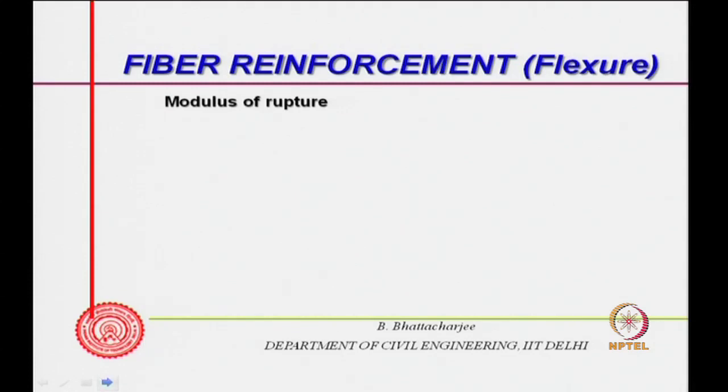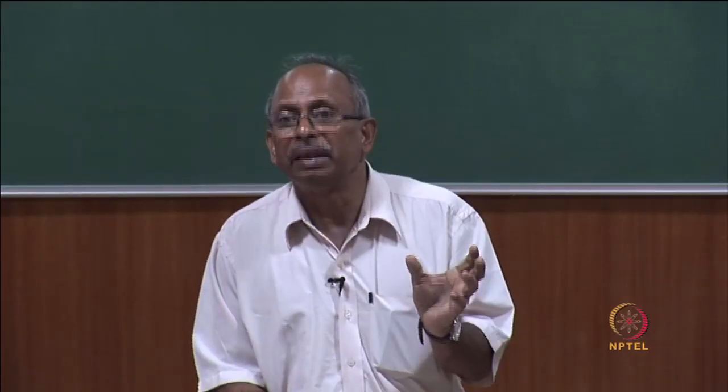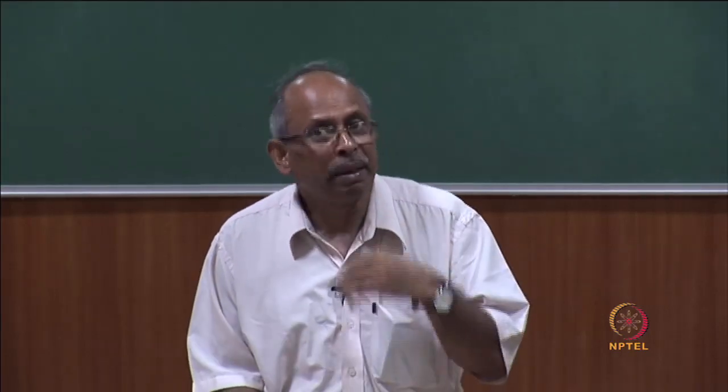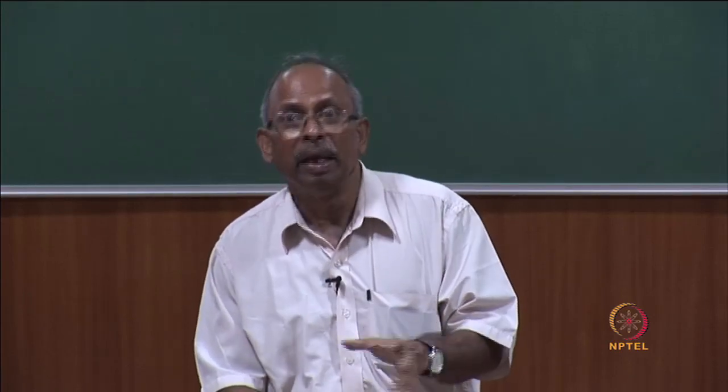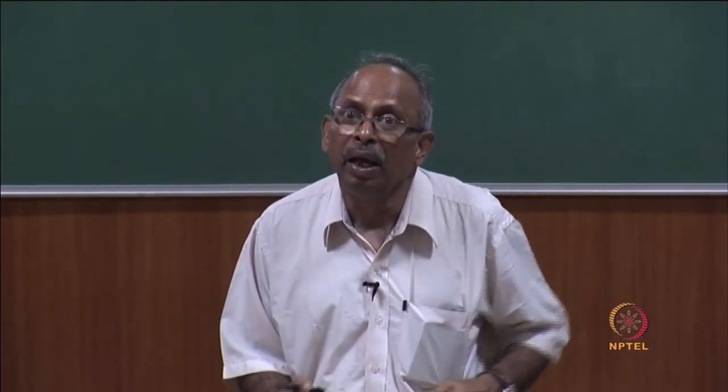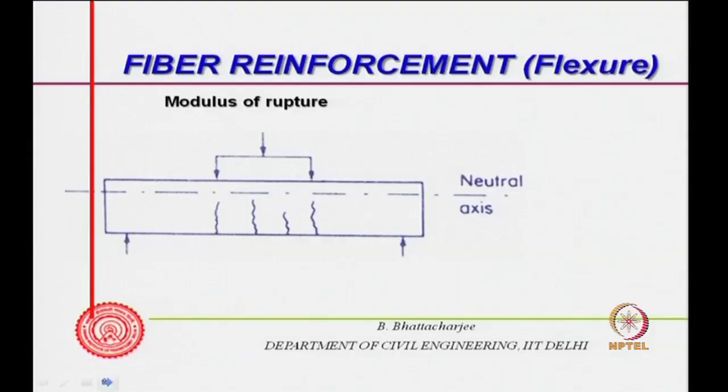Now, in flexure we are talking of improvement of the matrix itself, that is why we are talking of modulus of rupture. As I mentioned earlier, it is not the same thing as conventional rebar, it actually improves the material itself, and therefore we are talking of the modulus of rupture of the concrete. This is how we test the modulus of rupture, with third point loading, L by 3, L by 3, L by 3. In the Indian standard you have a 50 centimeter beam with 40 centimeter span, and the load P you apply, this is P by 2 and this is P by 2.